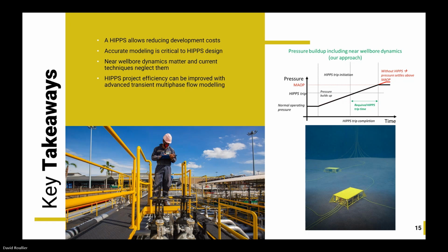Yes, sorry. The question was, and this will be our last question for the session: in most HIPPS design cases, it is depacking, fast depressurization from peak pressure that defines the HIPPS sizing scenario. Is this tool applicable for such cases? Yes. I have been in a project where the depacking was the sizing case, and that's accurate.